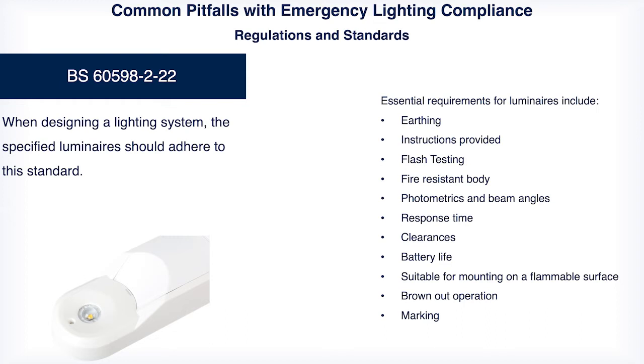Battery performance is one that I would point to all the time, because I think that when choices are made about luminaires, then often battery performance can be the biggest area where cost savings are maybe tried to be made, and yet the battery performance is really the critical part of that design. You know, a fitting that provides a 3-hour emergency lighting duration on initial install might not do that after 12 months, and regular checks are part of the testing regime, such that you need to do that full discharge within that period of time.